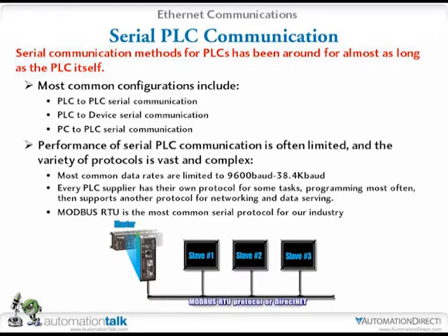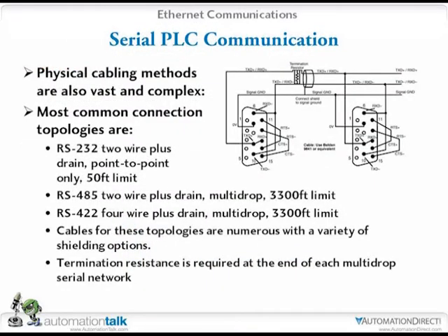Go to the next slide there, Tom. Can you see the hodgepodge of wiring? Can you imagine sitting out on the plant floor trying to wire up all this with a soldering iron and the DB connectors? Basically that's very similar to the serial remote I/O that originally was available on the DL205 product line. Now you see all the specs for it. The plus side is you have long distances, 3,300 feet. But when you max that out, you're done. But you've got 232, 485, 422, and you see all the specs there.